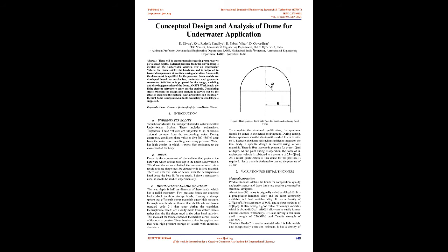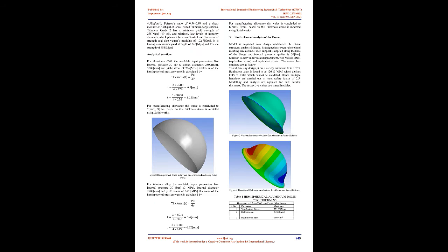Dome. The dome is the component of the vehicle that protects the hardware and acts as the nose cap of the underwater vehicle. This dome shape can withstand the pressure required. As a result, a dome shape must be created with the desired material. There are different sorts of heads, with the hemispherical head being the best fit for our needs. Before a structure is used, it should be studied experimentally.